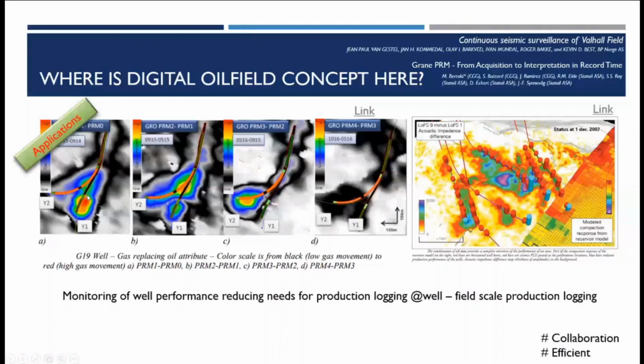In Y1, we have got the production screen just in here, and the black part is a blank, meaning there is no production from here. And in this particular branch, you have got production from this entire part. The places where you see is marked deep green, meaning that we have got inflow control valves out over there, which allows more oil to flow through. If it is permitting more oil, it will permit more gas as well, if you have got gas in the system. And that's how it is.